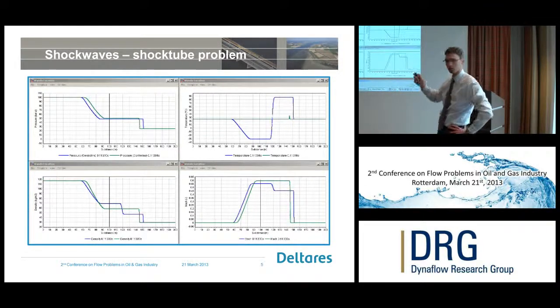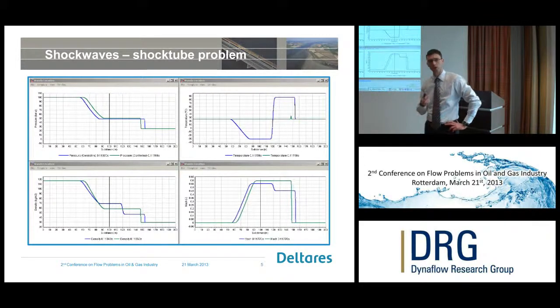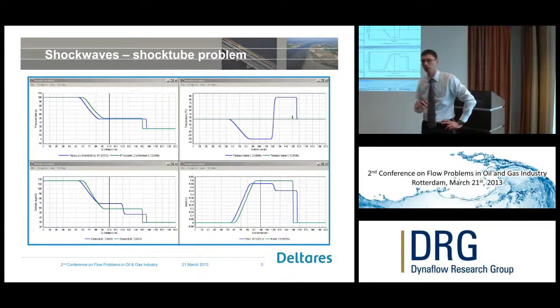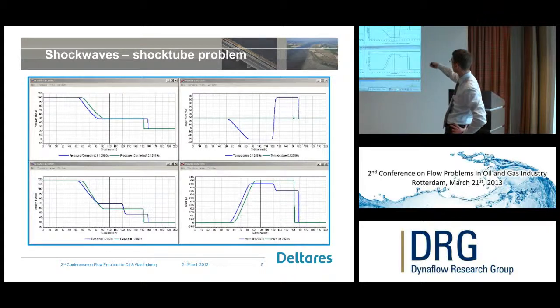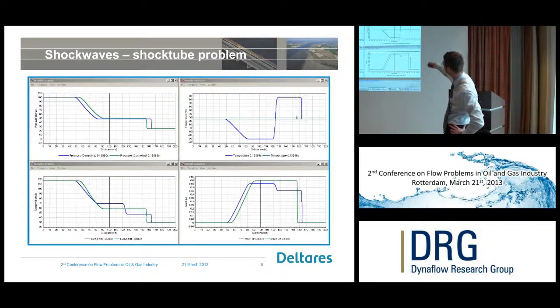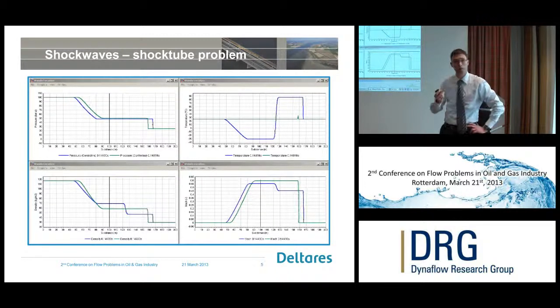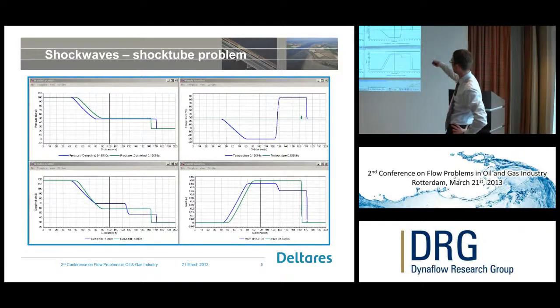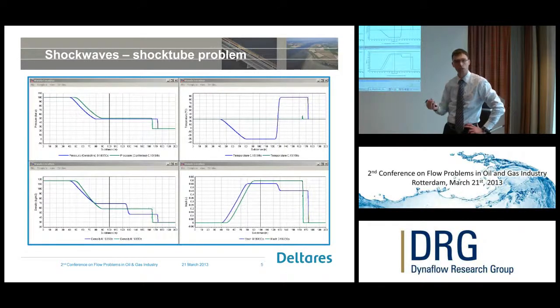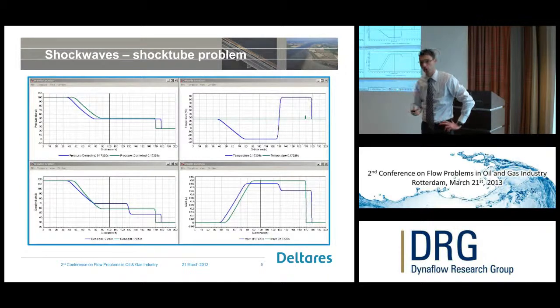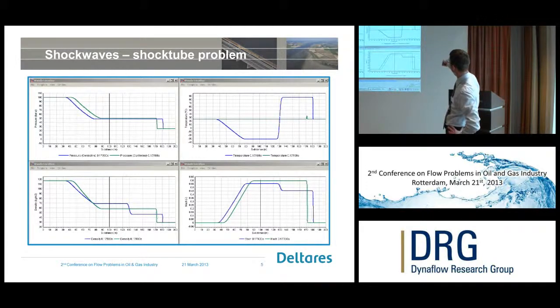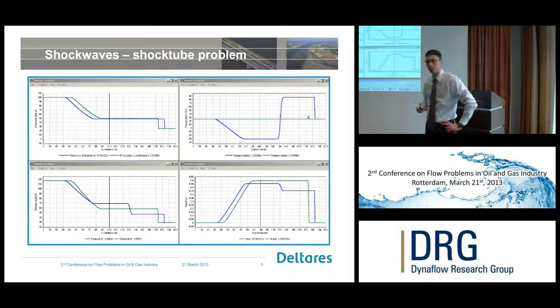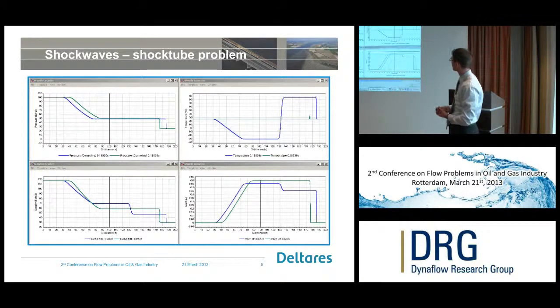But that's not all that happens, because you also have the expansion effect of the gas, and that's typically what you see over here with the temperature. What I need to say is that the blue line is an adiabatic system, so no energy goes into your system, and for the green line, I put the heat transfer coefficient so large that I try to make isothermal behavior, which is, except for this glimpse, almost the same.